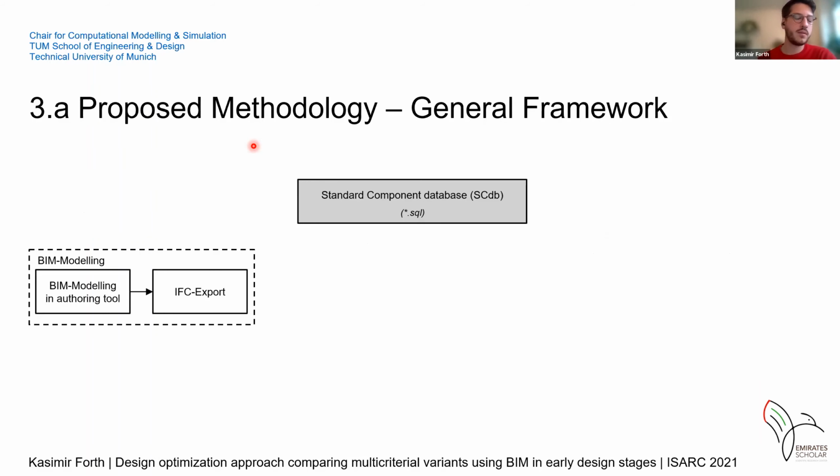So I proposed the following methodology, and I'm starting with a general framework. As already mentioned, I'm using BIM models, so I'm exporting an IFC file from the authoring tool. At the same time, my other input for the conducted analysis is this standard component database in SQL format. My first step is to map the IFC elements to the standard component database. How I will do that, I will explain later on.